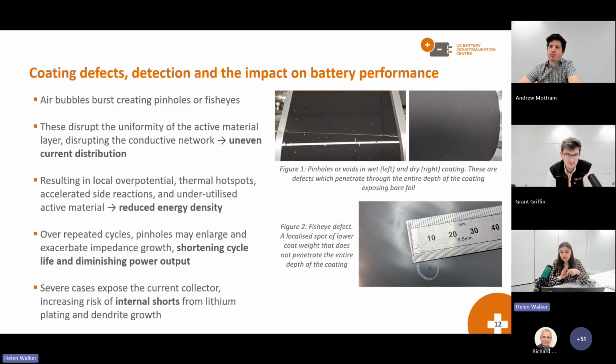As well as surface tension, we also need the contact angle of the slurry with the substrate in that model. And as you can imagine, the high edge prediction is very dependent on that contact angle measurement. We are able to measure that in the UKBIC lab, so we have reliable inputs for our CFD model. Is there anything that you'd add to that, Andrew?